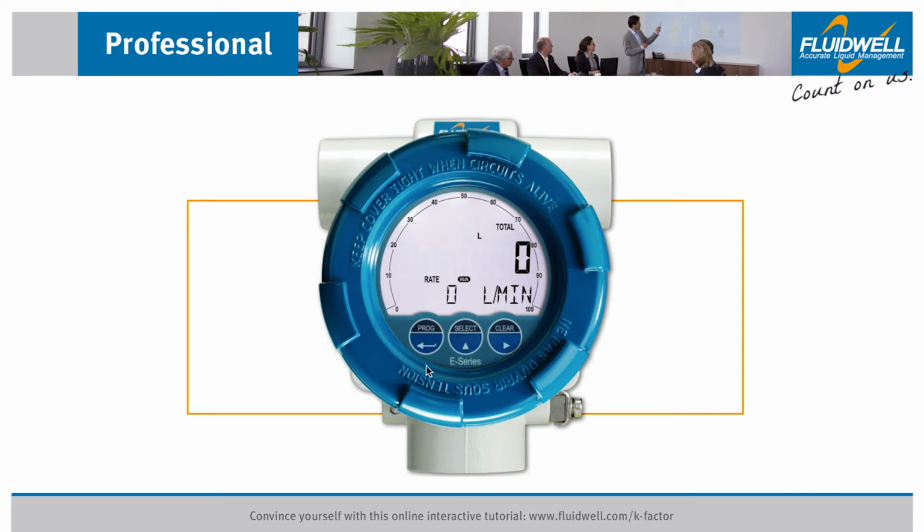Hold the Program button for 7 seconds. Menu 1 Total appears. You can use the Clear and Select buttons to navigate through the menu. Press Clear to go to Menu 4 Flow Meter. In this menu, we are going to configure the signal of the flow meter with the e-series. Use Select to go to Menu 4.2 Units. The Units menu is used to select the different unit conversion modes.